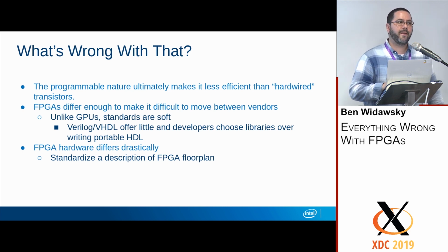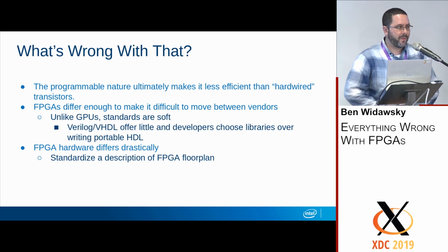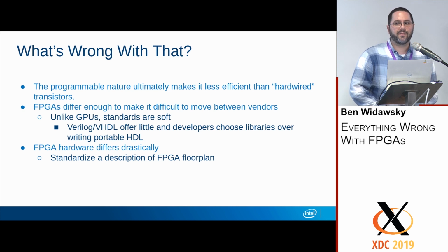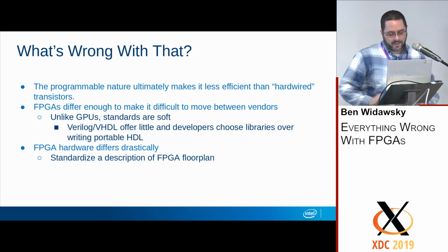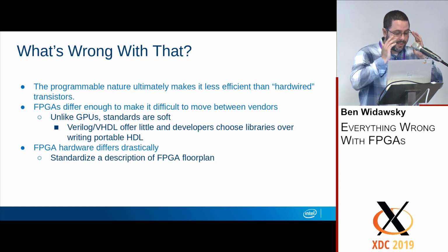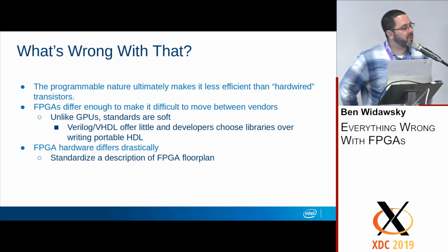And furthermore, the standards for the HDLs, which the primary ones are Verilog and VHDL, are not nearly as stern as I would say graphics standards are. So you don't have the same kind of conformance test suites. Different synthesis, or I should say different EDA tools will work differently and will accept different inputs and extensions. It's a little bit like GCC versus LLVM in that sense, or maybe GCC and a proprietary compiler would be a better comparison.